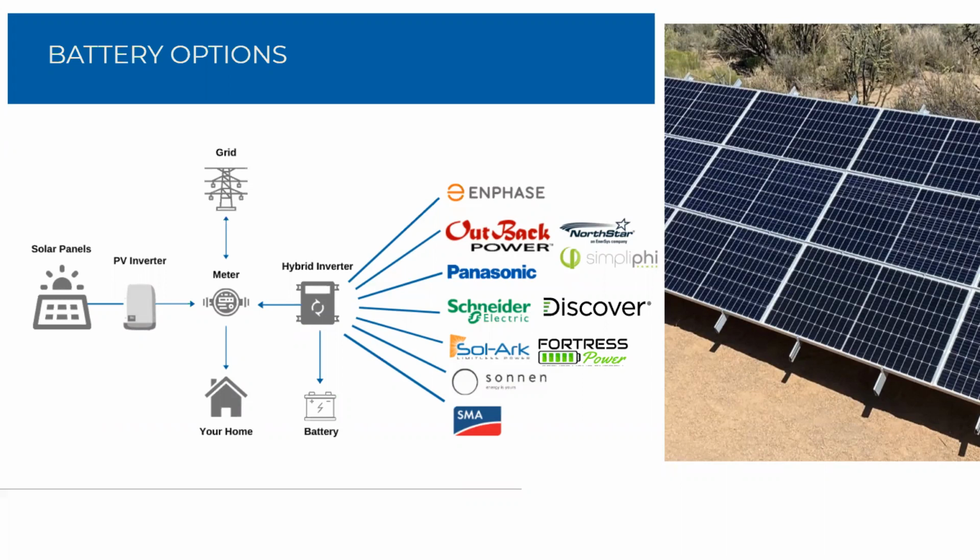So the capacity of your battery in kilowatt hours is most easily tied to the duration you're running your largest loads. That makes it a lot easier if your critical load panel is sized, let's just say, without any 240 volt loads, and it's only small 120 volt appliances that are drawing like 10 amps or less. Then your bank really could last for a long time. And here's another thing I will say. I would advise anyone who's considering a battery to slap on a Sense meter.